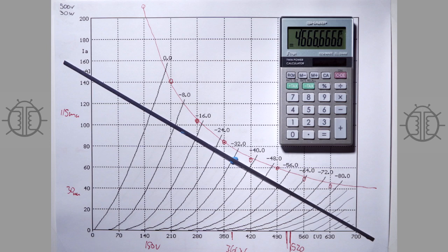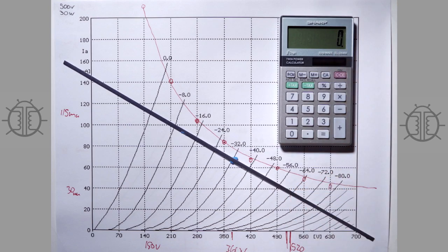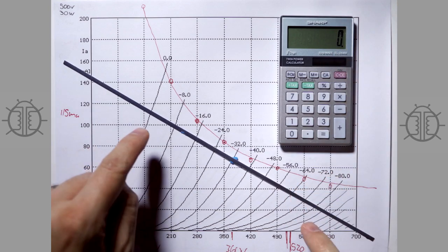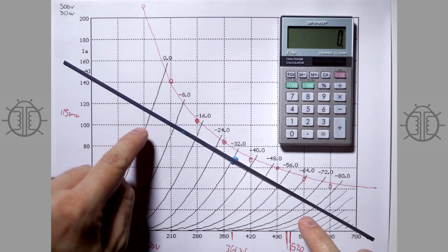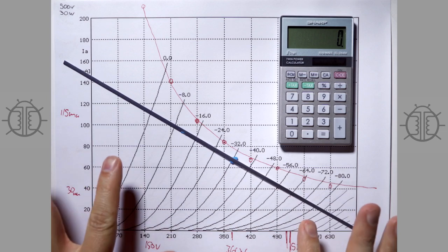And so we can calculate the output power pretty easily. If we assume that the wave is actually a sinusoidal wave, then all we have to do is figure out the peak-to-peak voltage, and then divide that by 2.83 to get the RMS voltage swing.